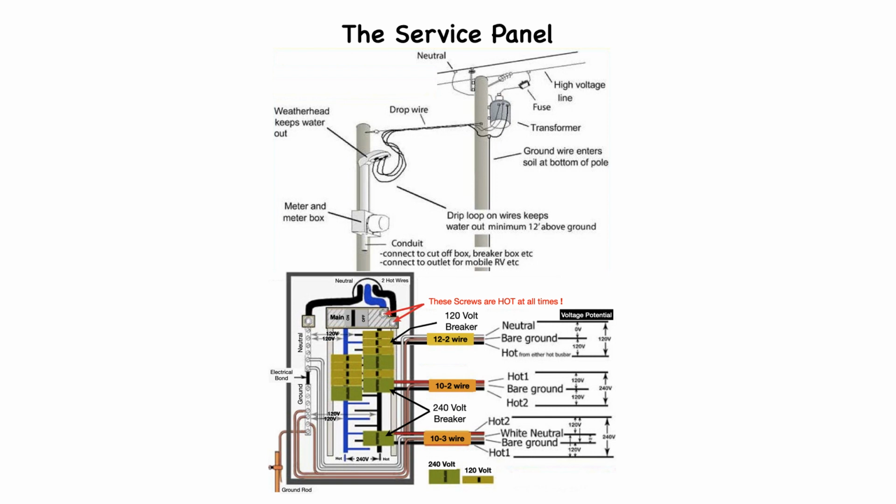In order for this to work, the circuit breaker must be in series with the 2 hot lines of the conductors, because it must cut power to all circuits. It is rated to be able to interrupt the total household load.